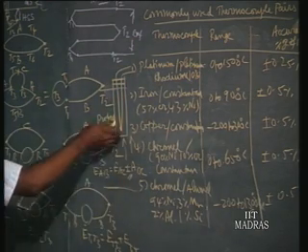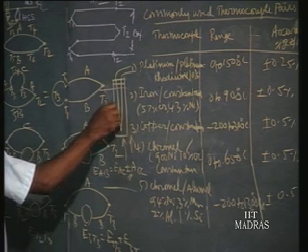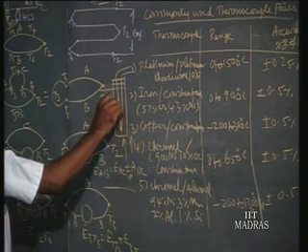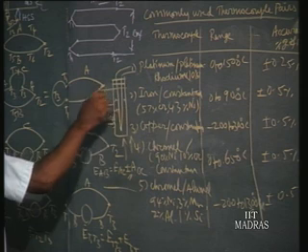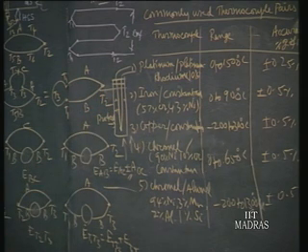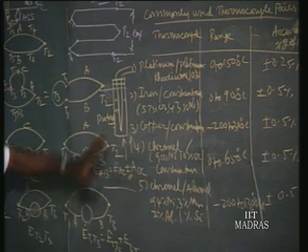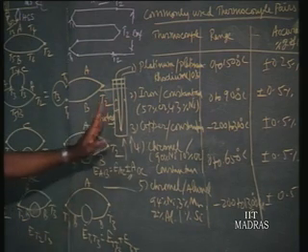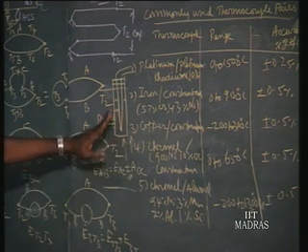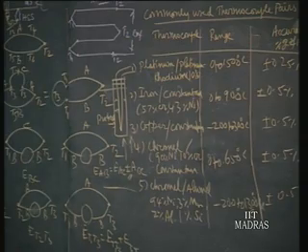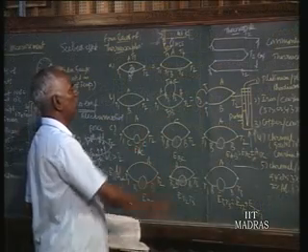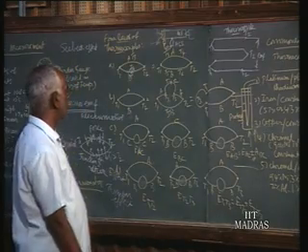At say 1000 degrees, you find this material absorbs some of the material in the vicinity. If you have any metal nearby, it also absorbs. So beyond 1000 degrees centigrade, we have to be careful that the wire doesn't get contaminated, or that when it absorbs such foreign material the calibration doesn't get changed. That is how you have to take care in actual usage of a thermocouple.